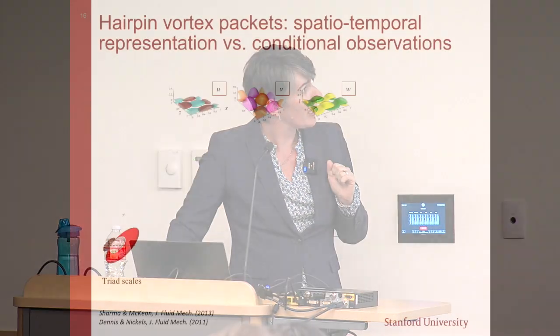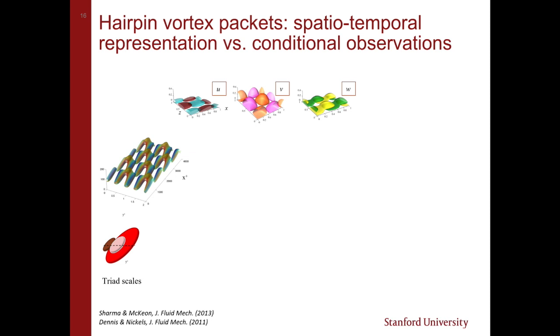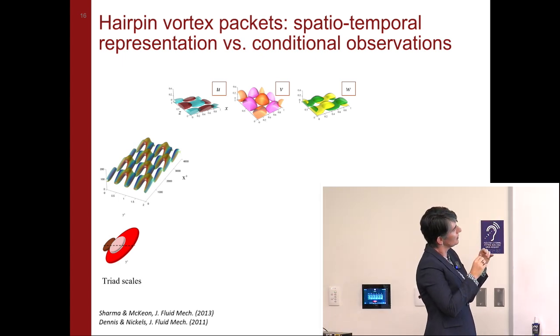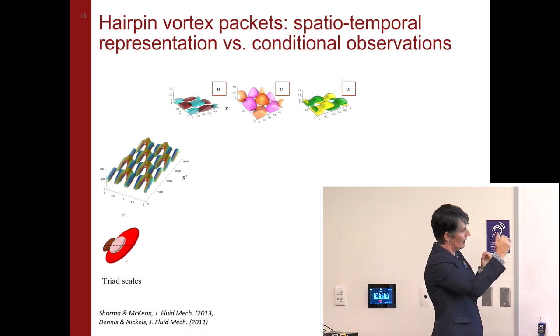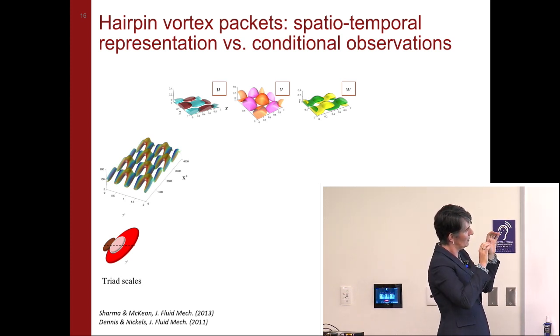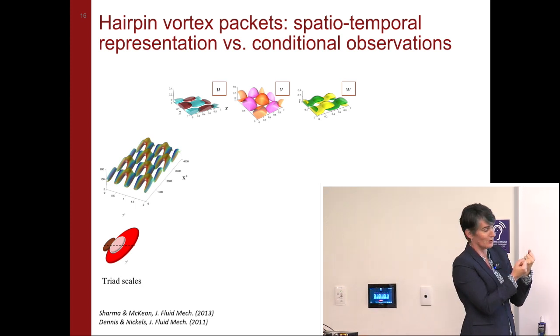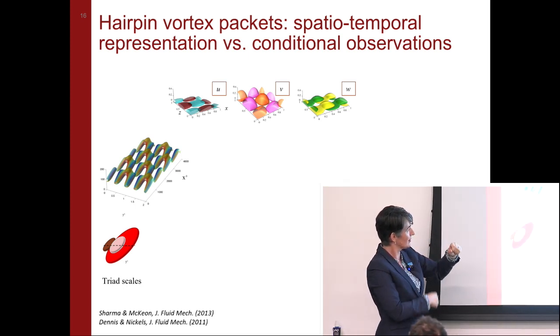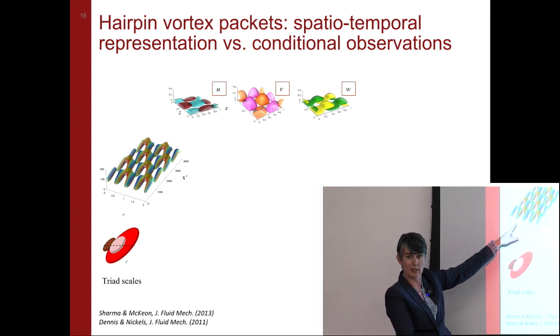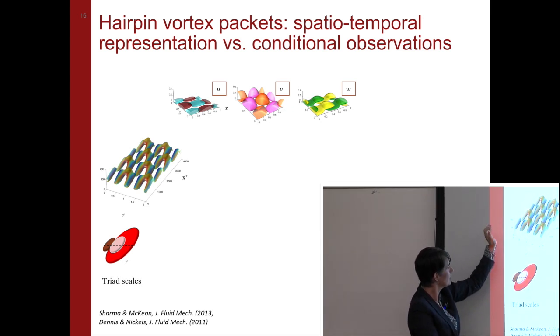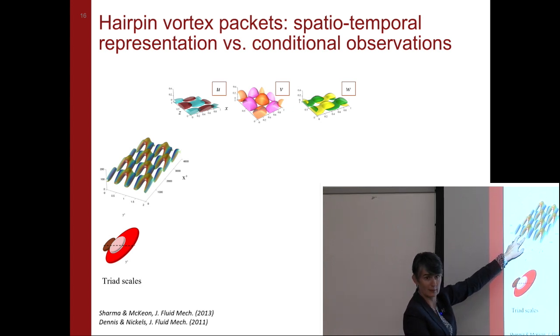Now, we also get hairpin vortices very cleanly. If I look at the U's and V's there, I can see that if I have an up V, and if you look at the spacing of each mode, there's a possibility at least that you have a low speed streak coming this way, and you have the U and V such that if you put the U and V together and then the W together, hopefully you can see, it's really a fluid mechanics class question, but if you put those together and I look at connected vorticity, whatever measure I want to look at, I will see these connected vortex structures arranged such that the rotation on the head is such that there's a low speed streak between the legs of this vortex.